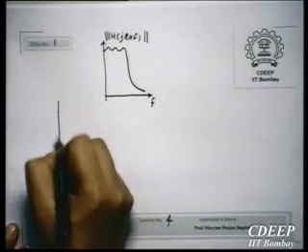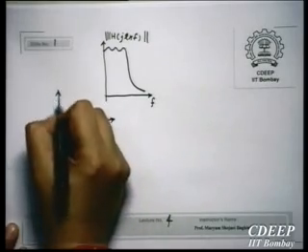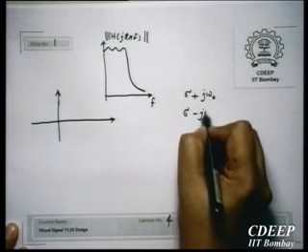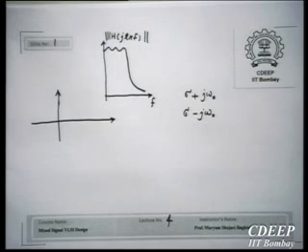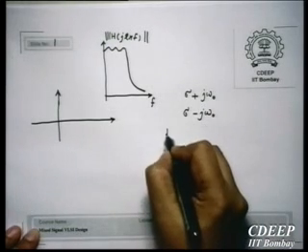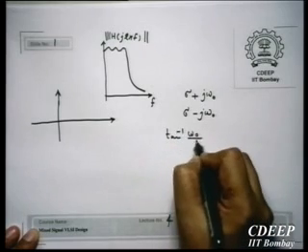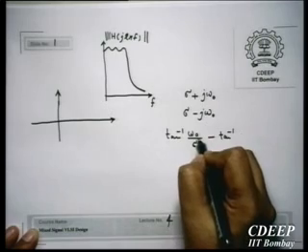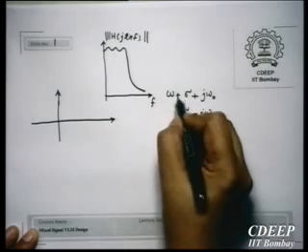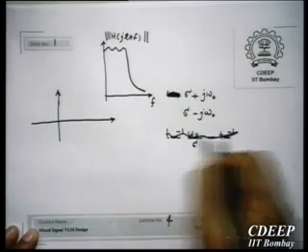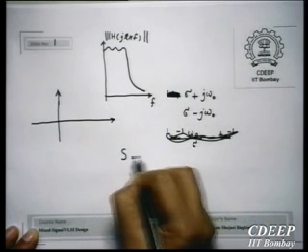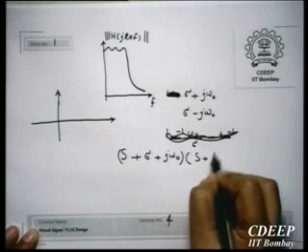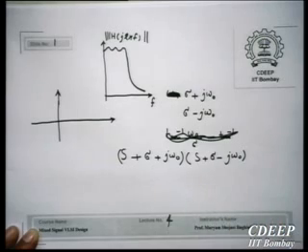See, simply if you look, what is phase essentially? If you have two poles, and definitely both of them should exist because the system is a physical system. Therefore, your phase will be tangent inverse omega 0 upon sigma minus tangent inverse, this is in fact omega, this is the pole. Therefore, your polynomial will be (S plus sigma plus j omega 0) into (S plus sigma minus j omega 0).